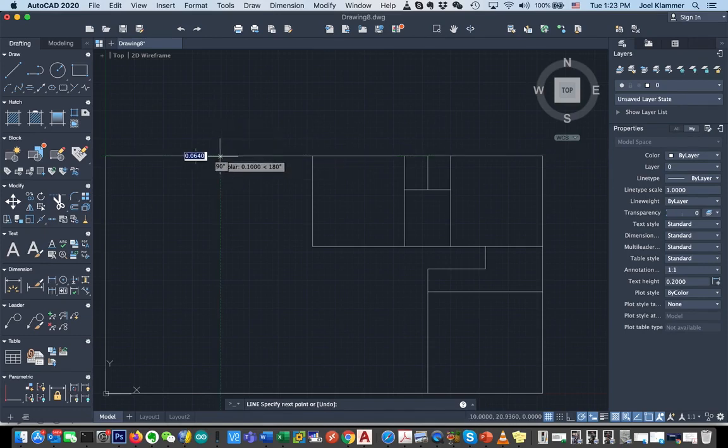All right. From there, I'm going to drag outward, and I want this to go out exactly 5 meters. Click. I need to go over 10 meters. Enter. Click, and then down to here and click. So there's my patio. I'm going to press enter to end the line command.